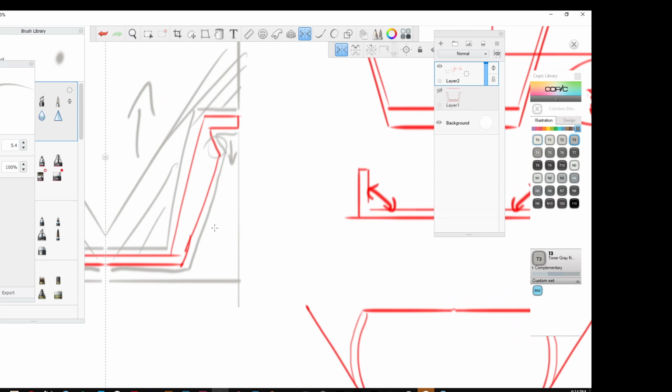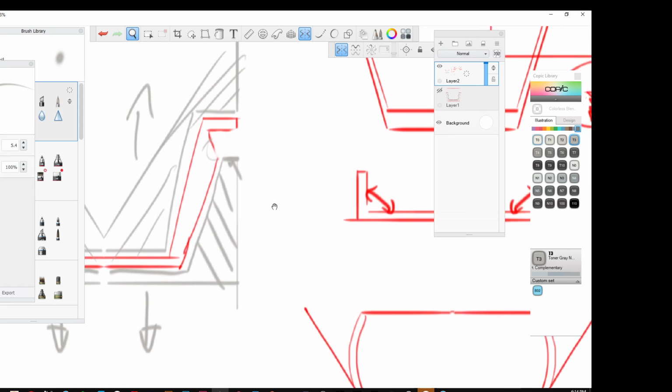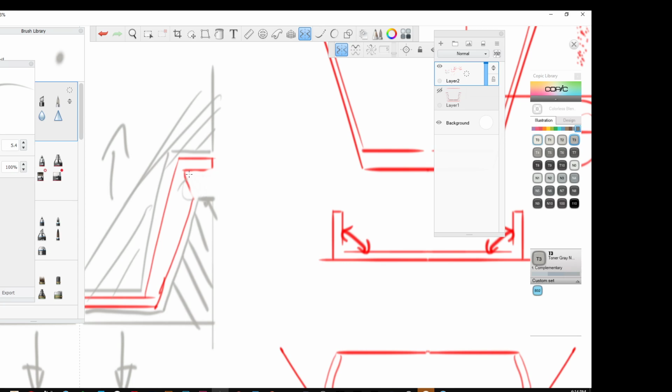But what you can do is you can do what's called a slide. So here, let's just erase that. The bottom tool comes down to here, which now can pull down perfectly clean. And then what happens is it's called a slide for that exact reason. There's a part that comes in here that is a tool. And literally what it does is it pulls in and out. So it goes in while the plastic's being poured, and then when the part needs to come out, this section slides out.